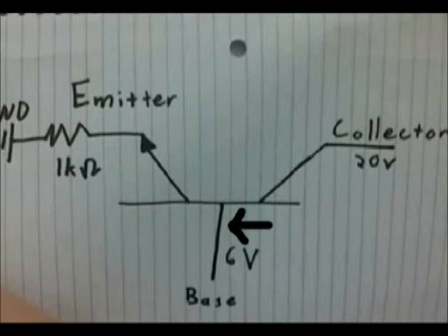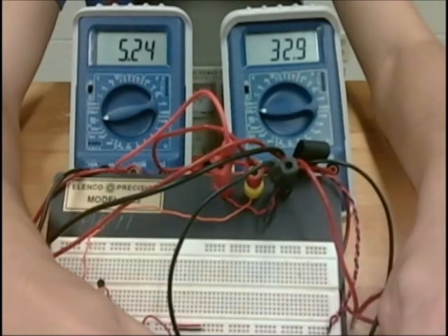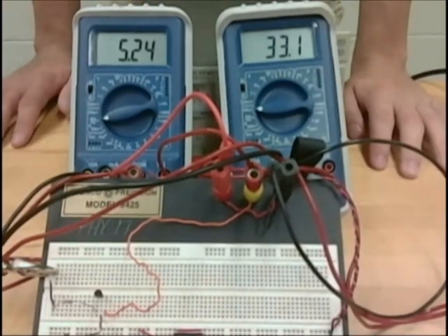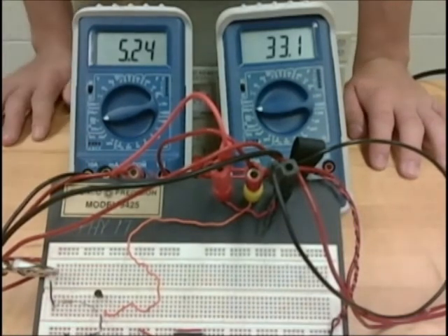To test the current in our circuit setup, we inserted a multimeter in series with the base current to measure our current across the base of the transistor. We also inserted a digital multimeter into the emitter branch to measure the amount of current going through that branch, as well as inserted a resistor to prevent our circuit from overloading. After we turned on our power supplies, the digital multimeters read out the current values across our base and emitter for our transistor. These values represent approximately 160 gain from the base current to the emitter current.